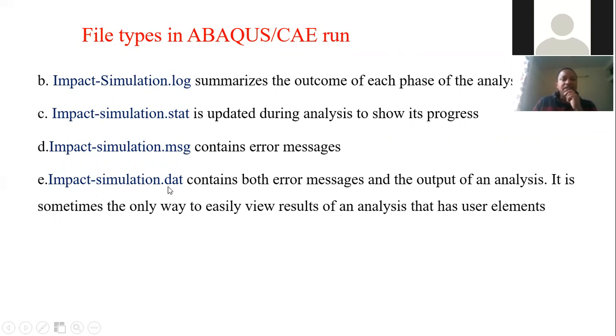The next is the .dat file. This file contains both error messages and the output of the analysis. It is sometimes the only way to easily view the results of an analysis that has a user element.